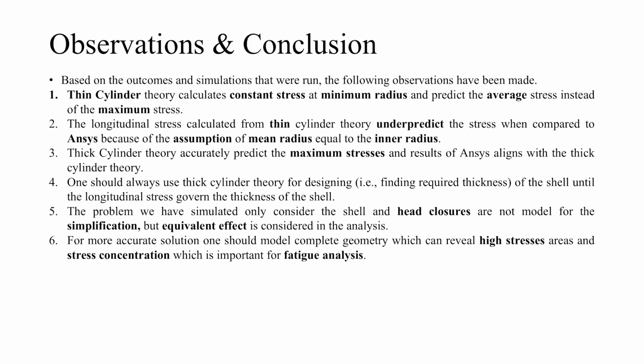Based on the outcomes and simulations that were run, the following observations have been made. The thin cylinder theory calculates constant stress and predicts the average stress instead of the maximum stress. The longitudinal stress calculated from thin cylinder theory underpredicts the stress when compared to Ansys because of the assumption of mean radius equal to the inner radius.